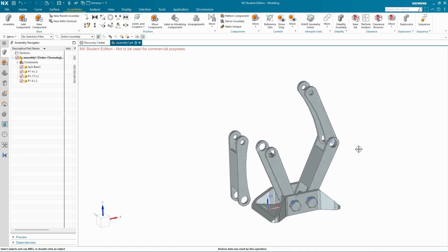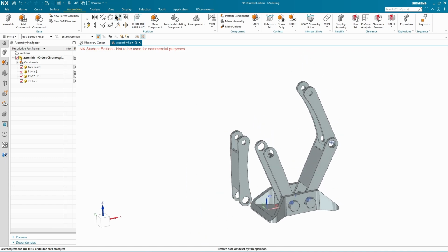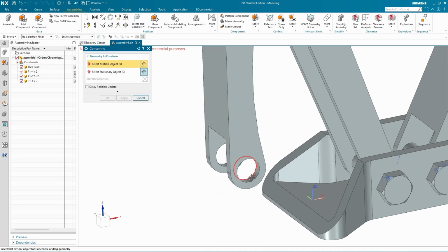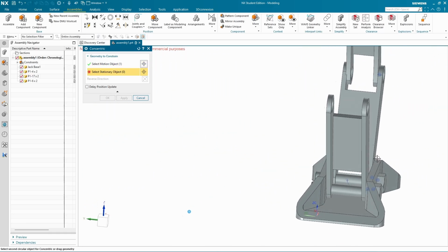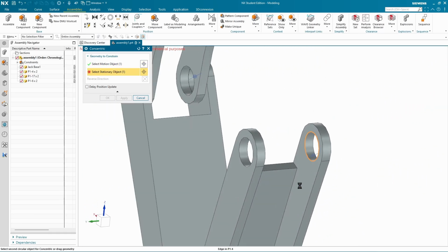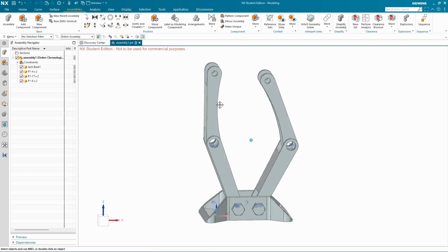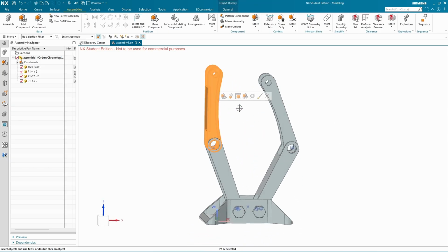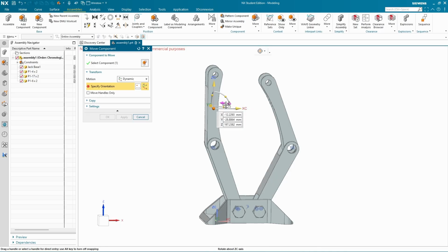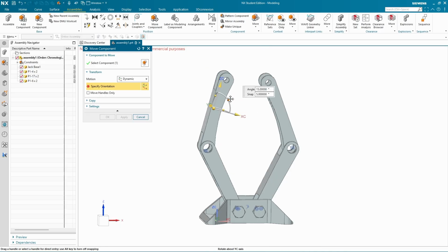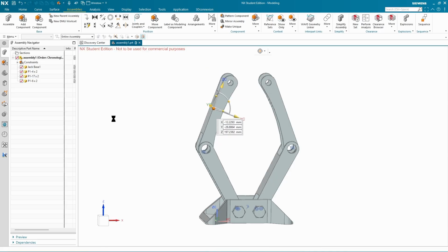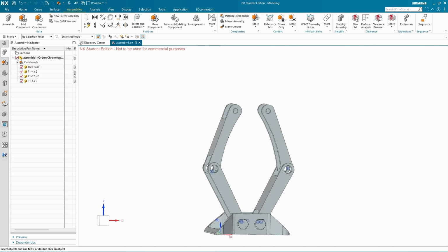It's good now. All right, so now I'm going to take this circle right here, concentric. Click on this guy right here, and then let's get to the inner area right there. Okay. Yep. Then we're going to rotate this guy: left click, move, and we're going to do 20 degrees. Okay. We may have to adjust this in a little bit, but we'll get there.